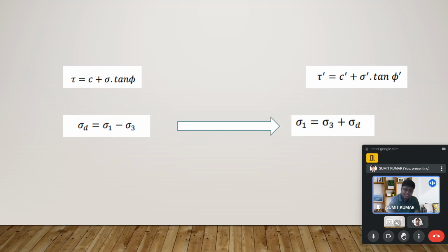When we were discussing initially, we talked about the total stress approach and the effective stress approach. In the total stress approach, we have stated that the failure envelopes developed during the different tests may not overlap with each other, but when we considered the effective stress approach, we found that the failure envelopes developed by any of the tests overlap each other, and hence the result is significant for us because we are stating the true result. Hence the effective stress parameters giving the value of shear strength, that is the effective shear strength, are more important for geotechnical engineers as compared to the total strength.